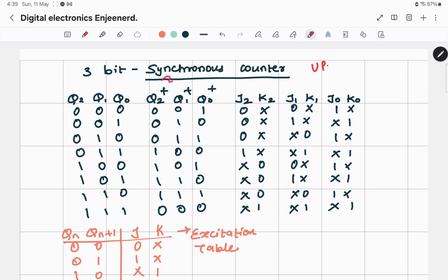So in this synchronous counter, you can have any sequence. It is not mandatory that you have to go from 0 to 1, 1 to 2, 2 to 3, and so on up to 7. We are designing this counter in a sequential manner, but in a synchronous counter, it is absolutely fine to have a state from 1 to 3 to 2 to 4 and back to 1.